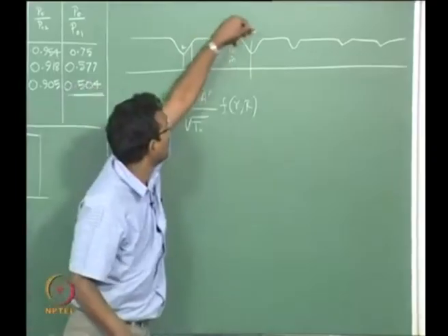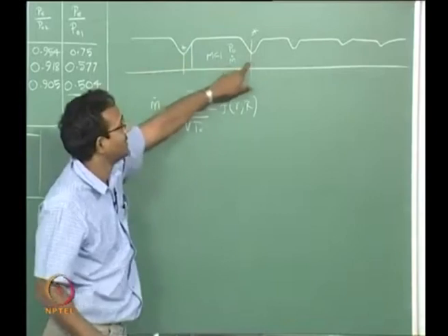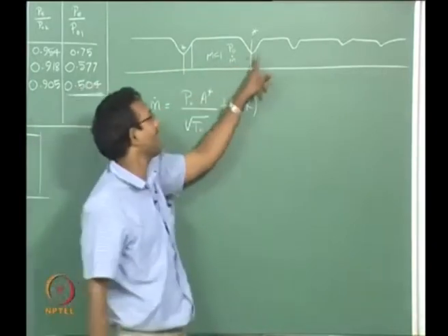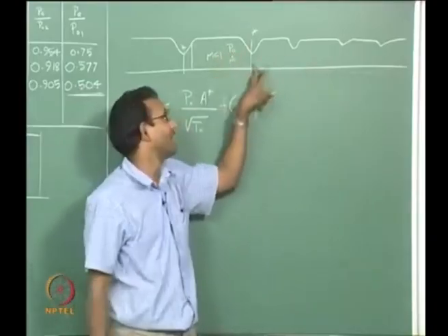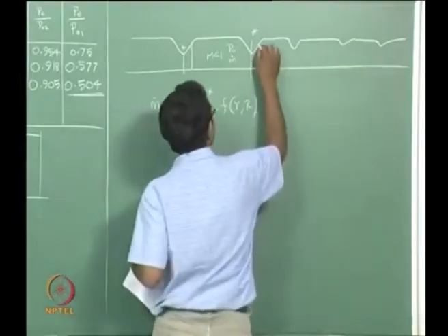So if I make a dent in this pipe up to a point where this A star is achieved here, then this will be choked again. Again I can have subsonic or supersonic. Subsonic, I told you already that it is very, very unstable. I cannot maintain many subsonic solutions. Let us assume there is another shock after this.